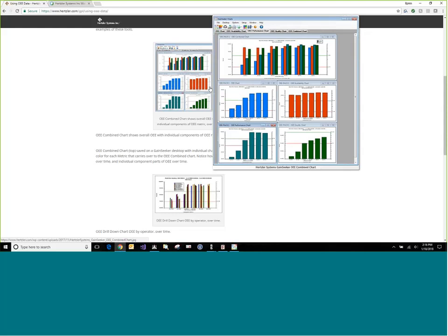And whether you are collecting data manually or automatically, you may want to set a downtime threshold. In other words, the machine must be down for 2 minutes before you consider it down and force the operator to enter a downtime reason. Finally, collecting piece counts might also be useful if your process is one in which a tool may need to be replaced or adjusted after a certain number of parts are produced. I know that we have worked with a couple of customers in setting up operator notifications based on that part count in the past. So there'd be some side benefits from collecting that data as well, besides the OEE.